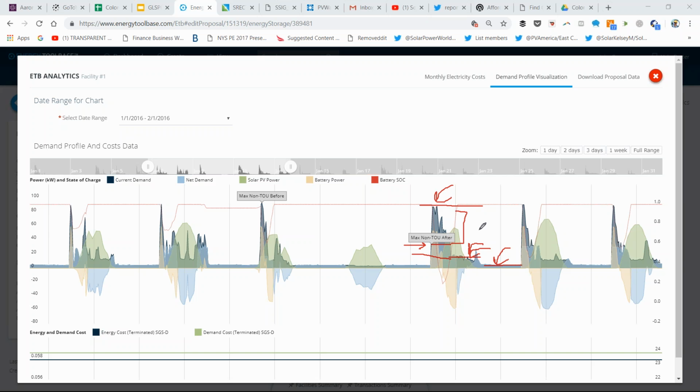And so the point is, by visualizing the data, your battery state of charge, your spiky versus your plateau peaks, you can develop a narrative to understand what's going on in your array, and that'll aid your ability to say, okay, well, should I start off with a larger battery bank or a larger solar array?